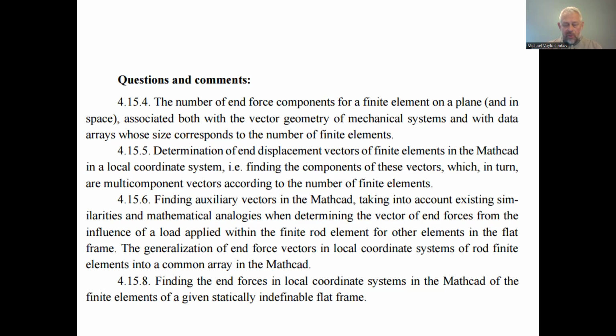So we have to substitute this load distributed within the finite element by the forces and moments acting on the ends of the finite element, because this is the concept of the finite element method that we have to consider the load concentrated at the nodes. Nodes are the ends of finite elements.